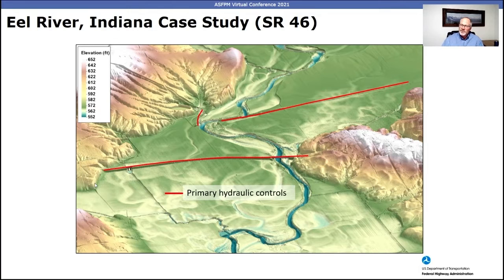And what these break lines do is that they force elements to be formed along those features to ensure that the edges are aligned. Now, in many cases, the channel break lines also act as hydraulic controls, mainly because the channel banks can control how much flow splits into the overbank and basically influence flow distribution. But it's not always readily apparent whether or not this is the case. So I consider it generally a best practice to include break lines along channel banks where they're pretty noticeable features, or especially when you're trying to evaluate how much flow spills into an overbank area.